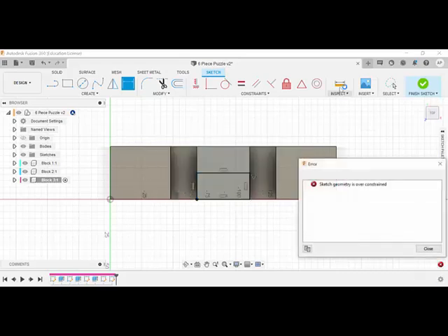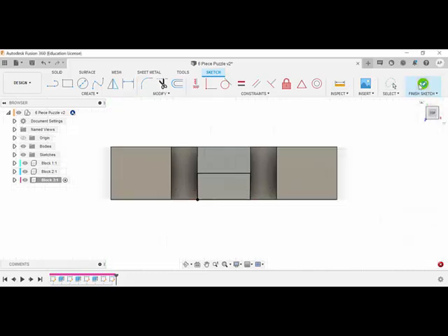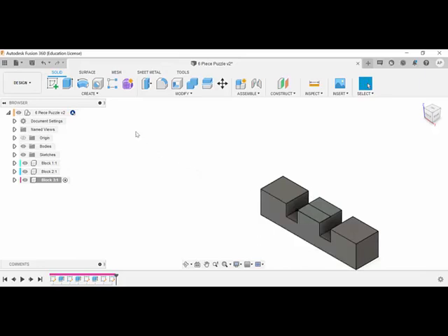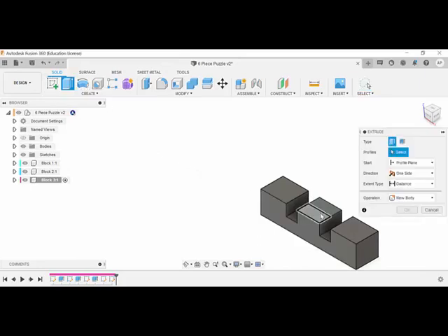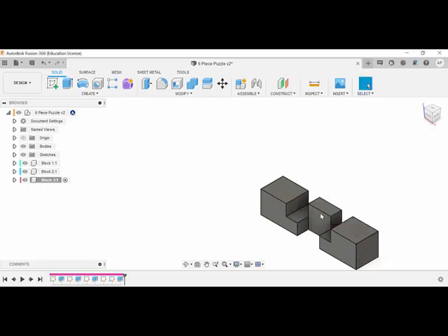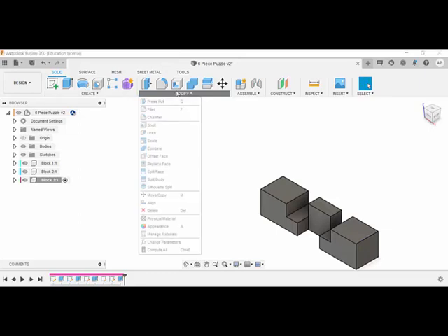So we can now finish sketch, get that orthographic projection going. We'll zoom down to that, and we're going to extrude that minus 42. And there we go. Now I don't think you need to see me chamfer the edges for the rest of these, but that's that step done. You can then continue, hold down shift, go across to modify, and then chamfer those 8 edges.